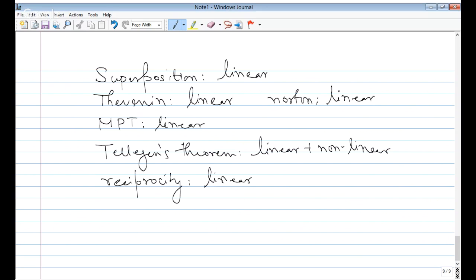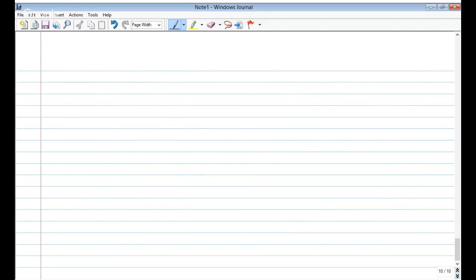The next question is from Karthi. A DC chopper is used for separate regenerative braking of a separately excited DC motor. The DC supply voltage is 400 volt. Motor has armature resistance 0.2 ohm. Then Km, that is the motor constant, is 1.2 volt second per radian. The average armature current during regenerative braking is kept constant at 300 ampere with negligible ripple. For a duty cycle of 0.55 for a chopper, power returned to the supply is?